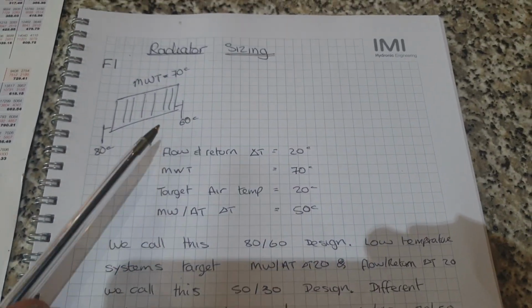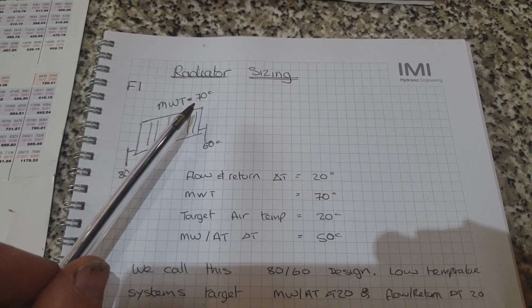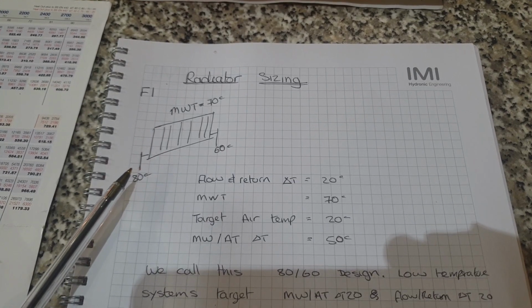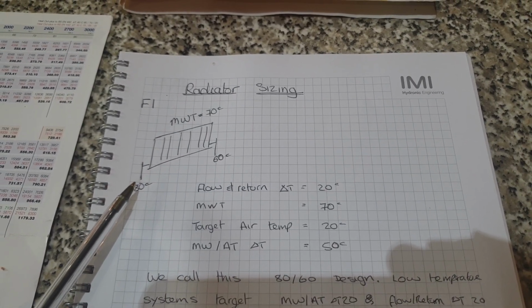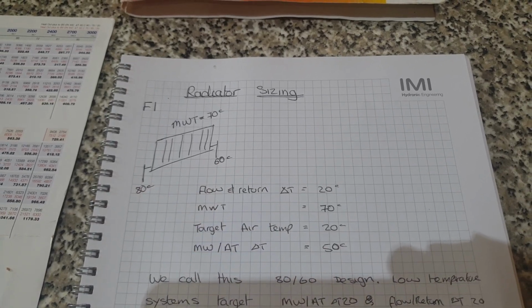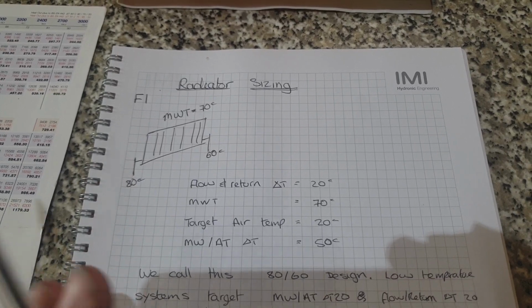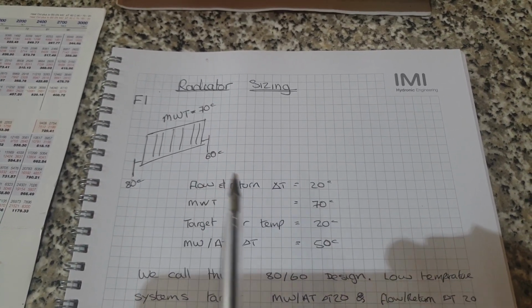So delta T 60 is assuming a mean water temperature of 80. Now it might be possible to understand that's not really that possible, but I guess for that we'd end up with a flow temperature of 85 and a return of 75, I guess, because we're not going to be getting up to 90 flow temperatures. I'll comment on that a little bit more later as well, that delta T 60 rating.